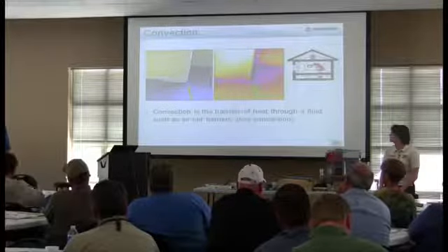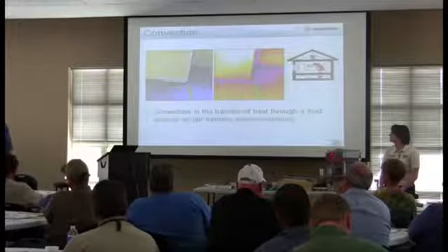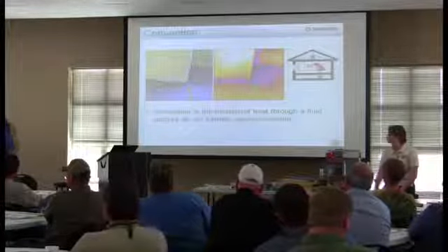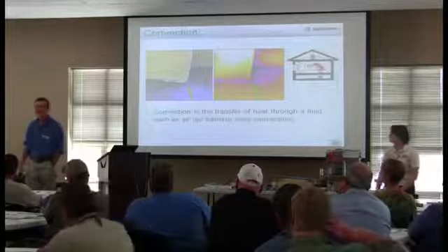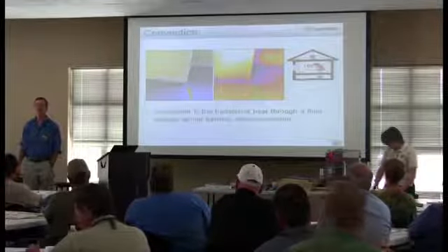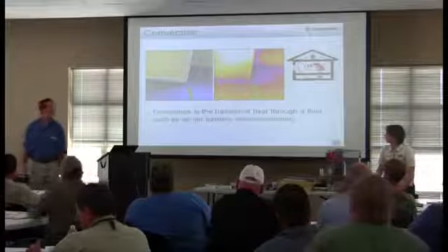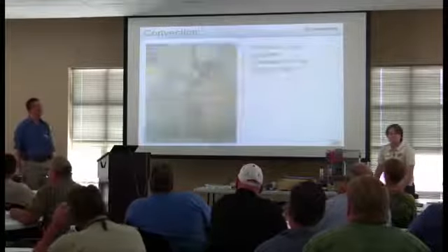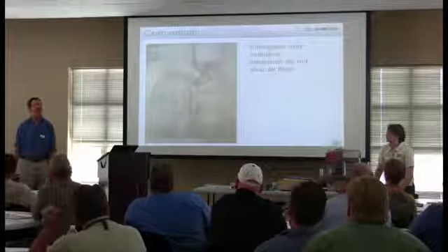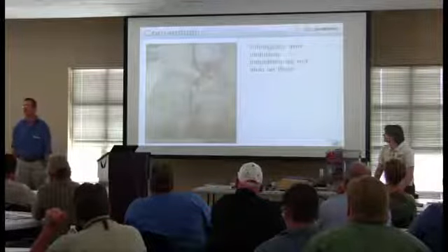So basically the simple way to slow down or stop convective heat transfer is to do what to the building envelope? Seal it up. And if we're going to seal it up, we need to use materials that are intended to be air barriers, or air sealing materials, right? And so, John, the product that you sell is a great insulation product, but fiberglass is not, and nor was it ever intended to be, an air sealing material, right?